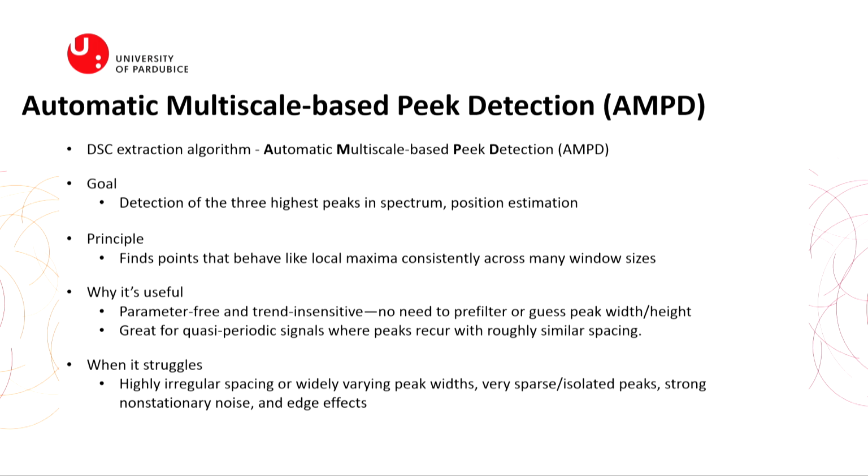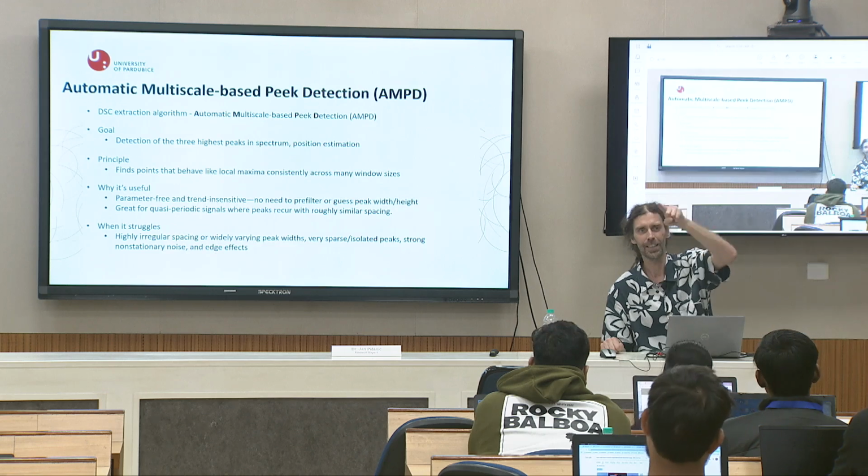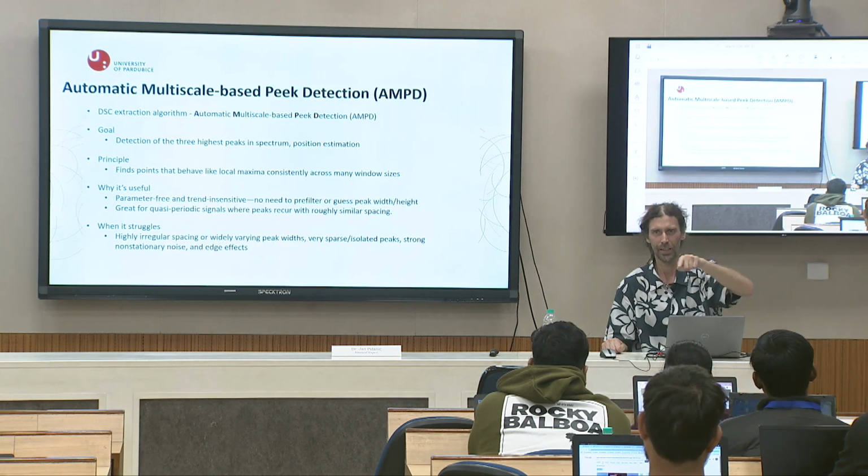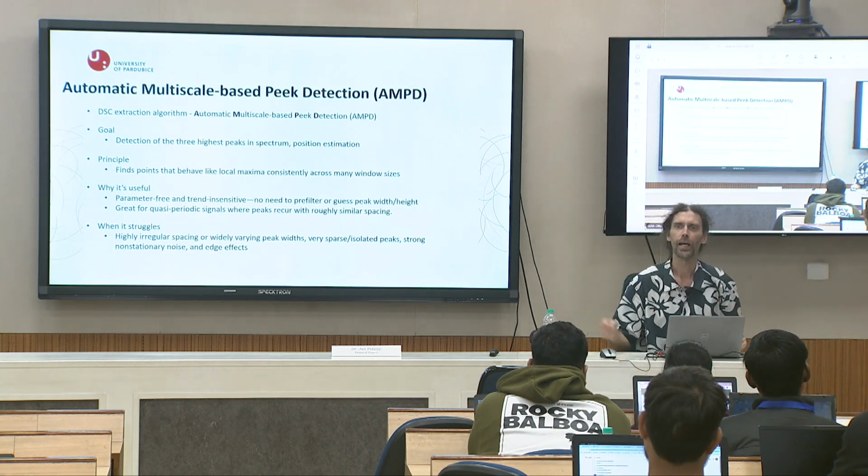If your signal is without any noise, you don't need this algorithm. Why? Because you always detect these 3 maxima without any problem. But if it is noisy, then you will have jittering of your signal. And with this jittering, it is hard to make a decision: where is the maximum in this jittering? And for this reason we use this algorithm.